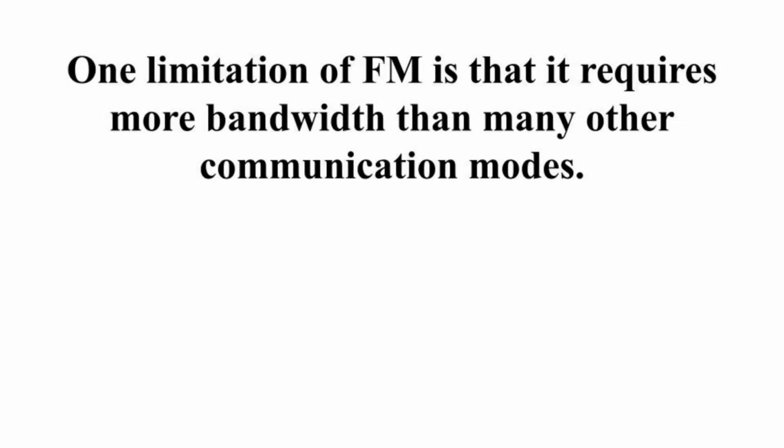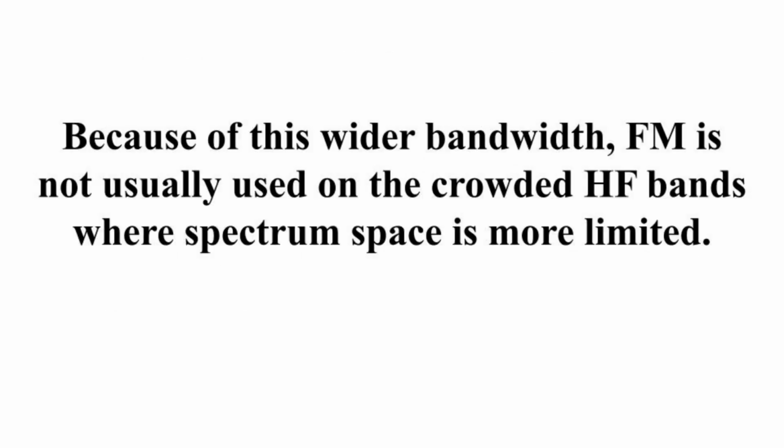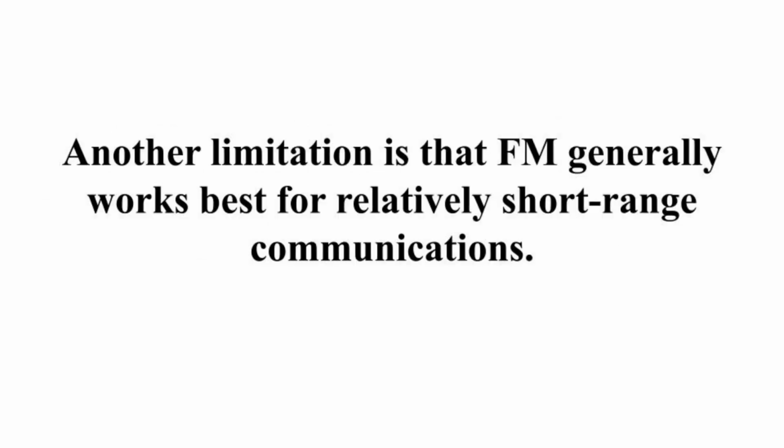Limitations of FM. One limitation of FM is that it requires more bandwidth than many other communication modes. As we discussed earlier, a typical FM voice signal may occupy around 12 to 16 kHz of spectrum. Because of this wider bandwidth, FM is not usually used on the crowded HF bands where spectrum space is more limited. Another limitation is that FM generally works best for relatively short-range communications.